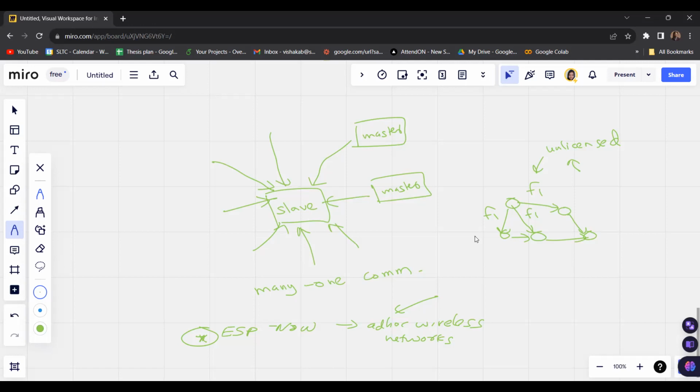That is possible using this ESP-NOW protocol, and you can directly send to the specific person that you want to send the data to. That specific person can be found using the MAC address of the receiving microcontroller. You can define that MAC address as the receiving microcontroller MAC address in the code, and that will enable you to easily connect with the receiving device.